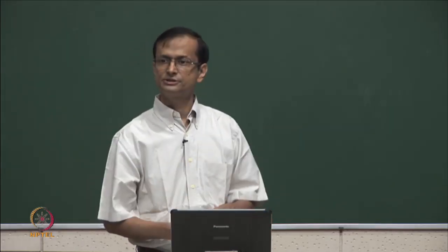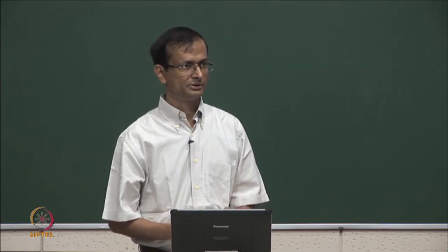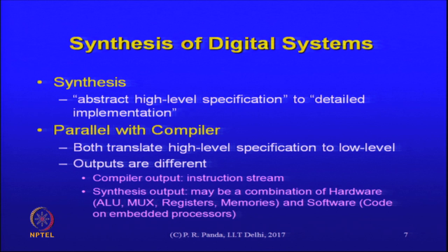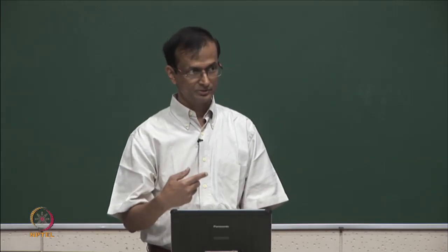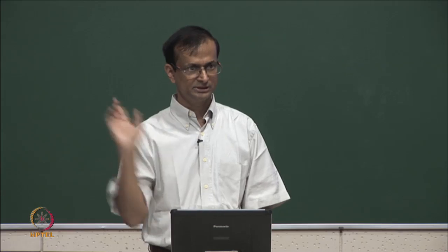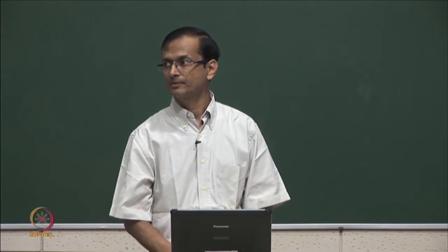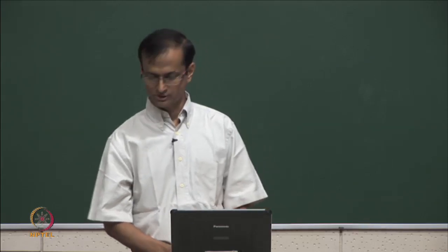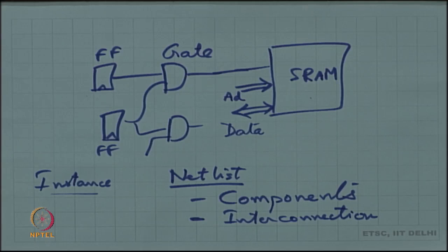When you write an instruction sequence, what is the assumption about the execution of that sequence? Yeah, there is a sequential execution. The processor is going to pick up one instruction at a time, okay, and execute it. Is the same the case in the hardware in this netlist that we draw? No. What is the case here? I had 5 components here, what is the assumption about the order in which these 5 components would be evaluated or executed?